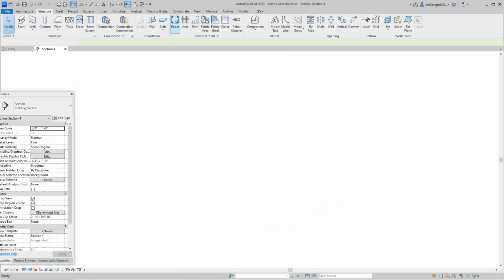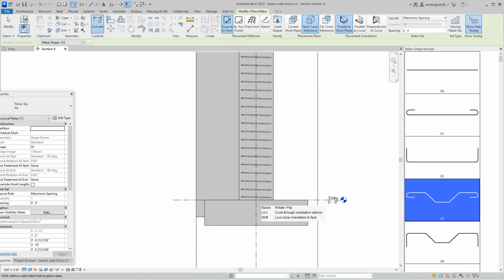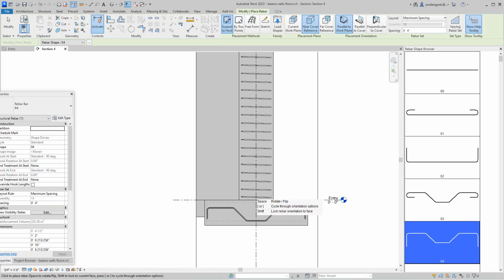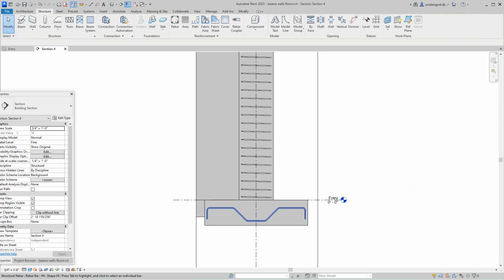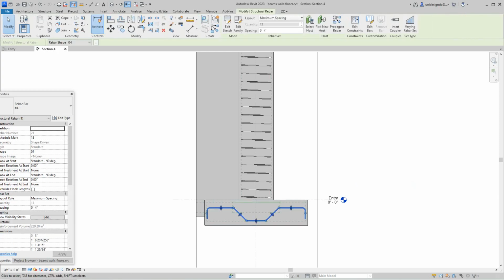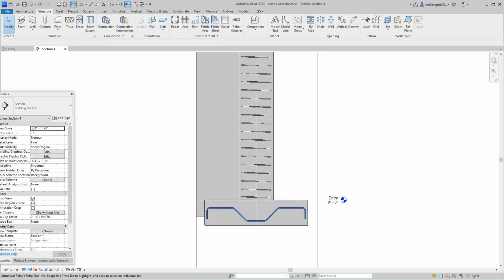So here we're going to rebar, and then I got to make sure this is parallel. So let's go with this shape here. And let's put it that way. And then here I'm at 4-inch spacing, so I'm going to cancel that here and select it. Let's make this maybe 9 inches, or let's say a foot. Well, let's make it 9. It don't really matter. So I've got that 9 spaced out there.